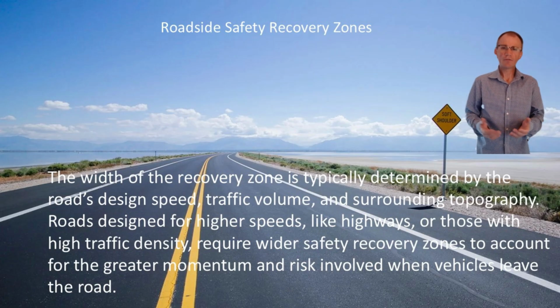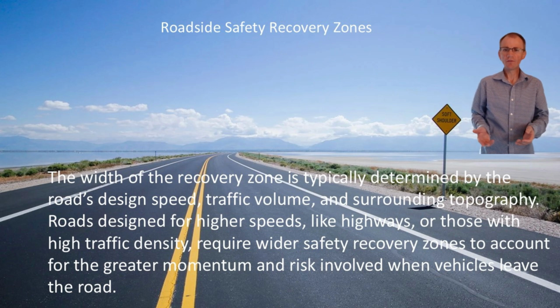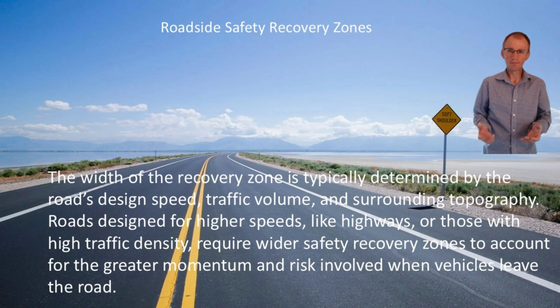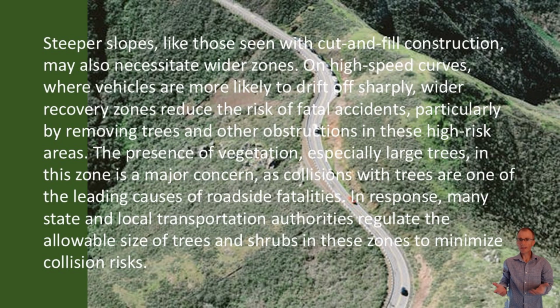Roadside safety recovery zones. The width of the recovery zone is typically determined by the road's design, speed, traffic volume, and surrounding topography. Roads designed for higher speeds, like highways or those with high traffic density, require wider safety recovery zones to account for the greater momentum and risk involved when vehicles leave the road. Steeper slopes, like those seen with cut-and-fill construction, may also necessitate wider zones.